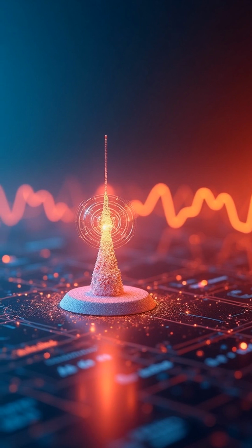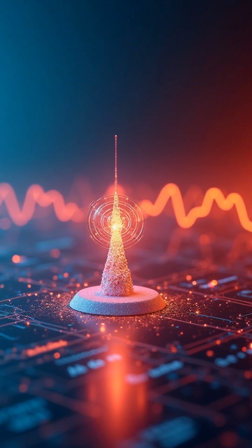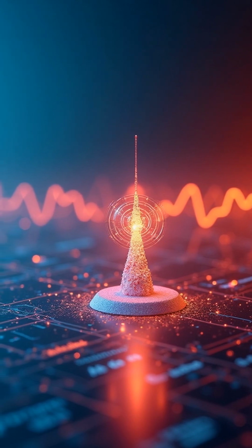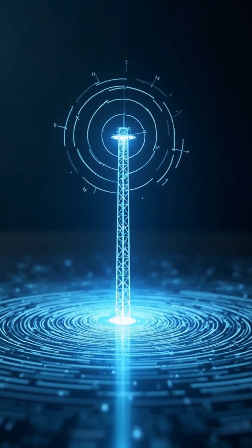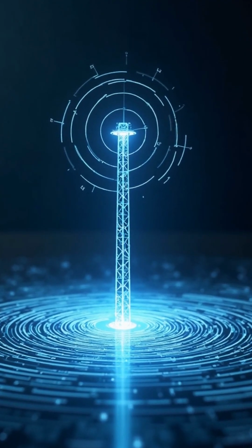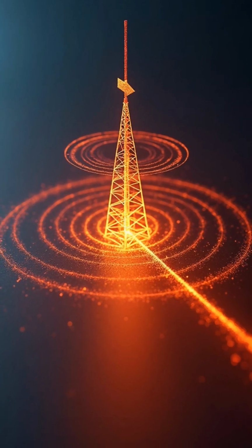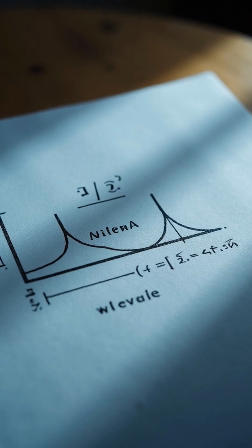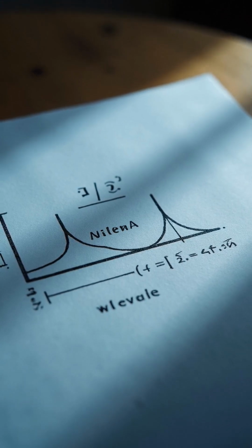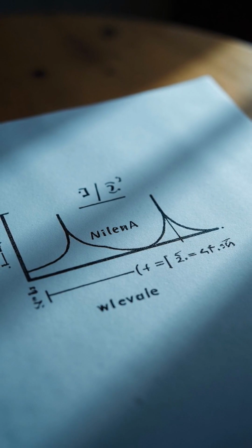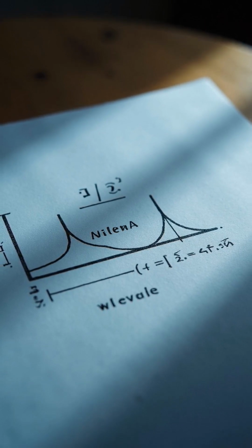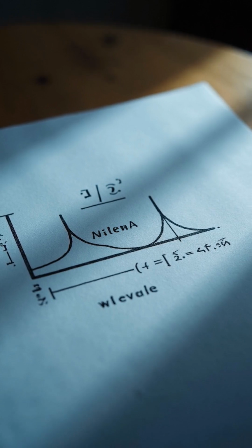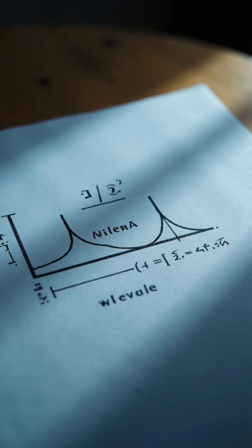The shape and direction of electromagnetic wave radiation depend on antenna type, wavelength, and antenna length. A dipole antenna produces a donut-shaped radiation pattern. A Yagi antenna focuses the signal in one direction. Antenna length is typically a fraction, e.g., λ/2 or λ/4, of the signal's wavelength.